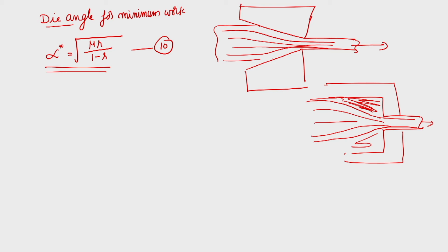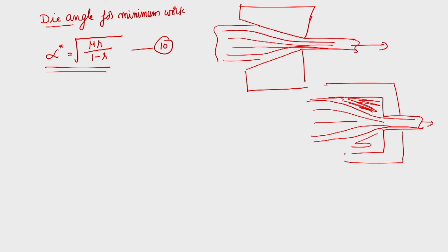And sometimes the stress developed at the center is higher than your applied drawing stress also. That means if you compute based on the mean stress, you will find that at the center it may still be higher than that. So the excess stress on the center line above that required for drawing is given by the difference between the center line stress sigma max and the average draw stress, sigma max minus F by AF.